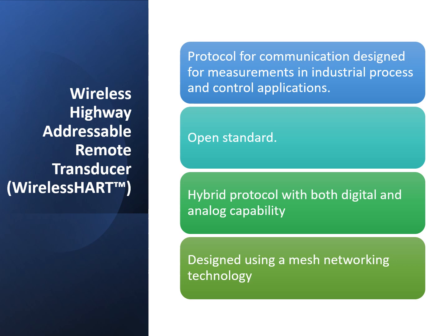WirelessHART is designed using mesh networking technology. In a mesh network, a device can serve as a router for messages from other devices. This capability allows the extended range of the network and enables reliability through the redundant communication routes in a radio environment that is commonly found in process networks.